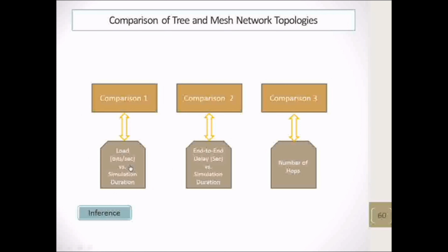The input is 12 volt and the output is 5 volt, because Zigbee operates at 5 volt only. And this simulation is done with Proteus. Next, this is the hardware for the serial communication setup. Here IC 7805 is the voltage regulator IC, and these capacitors are used for safety.